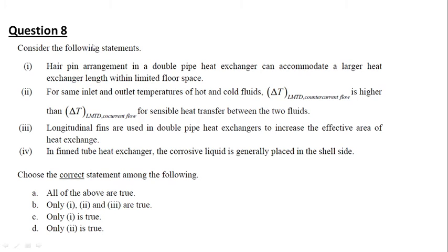All the three statements are correct, but option 4 is incorrect. Here we need to note that it is given sensible heat transfer, but if there is a phase change, then the LMTD of counter current and co-current will be the same.